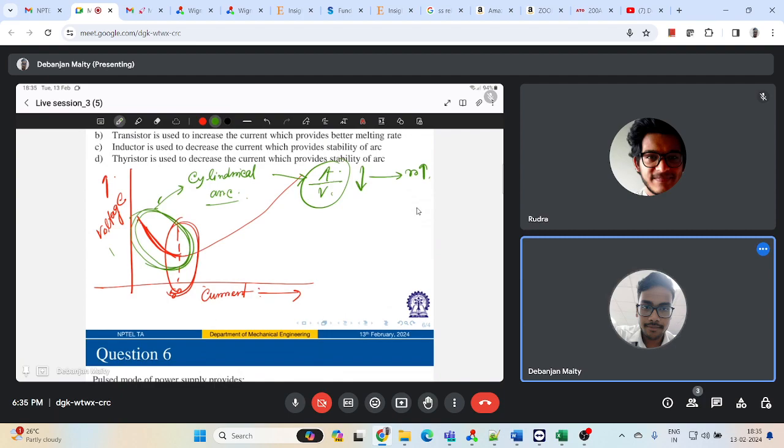So at this region, a thick and high current arc loses less heat and essentially burns hotter. And this results in higher conductivity as compared with a thin and low current arc.